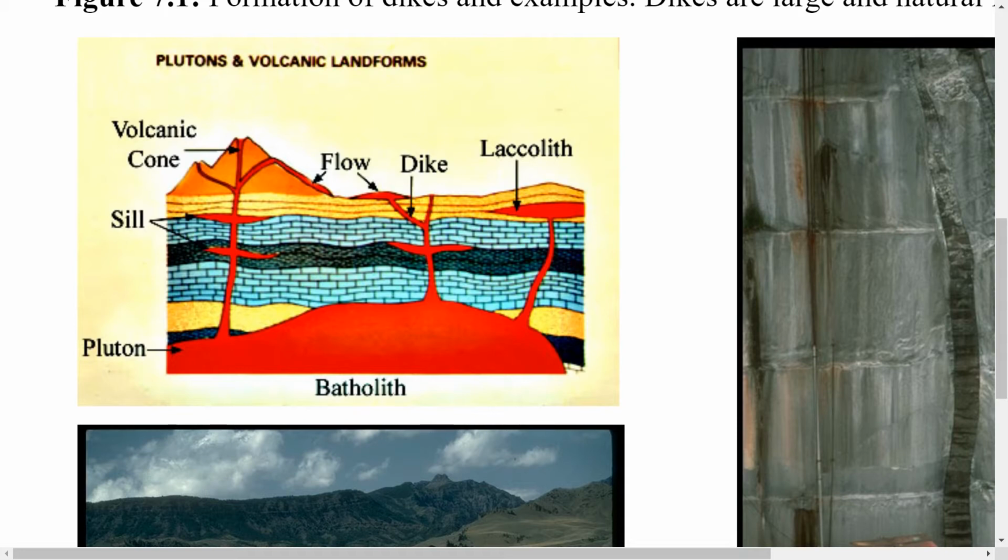We're going to see that there might be two reasons for this. The principal one is a change of the state of stress. It might happen that because of the different properties of these layers, the horizontal stress may be larger in this carbonate rock than in here. So when it gets to there, it finds that the minimum principal stress is now vertical, and it prefers to open up, pushing up the rock rather than pushing it to the sides.